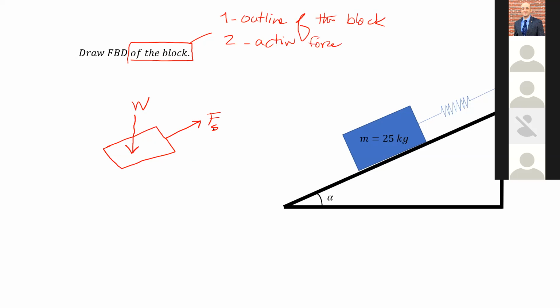Okay. What about reactive forces? What kind of reactive forces do you see on here? There's the normal force, perpendicular to the surface, N, and then there is a friction force. Okay. Which way would you put the friction? I'm pretty sure a lot of people had this question. You put it going to 2 because the block is trying to slide to the left.